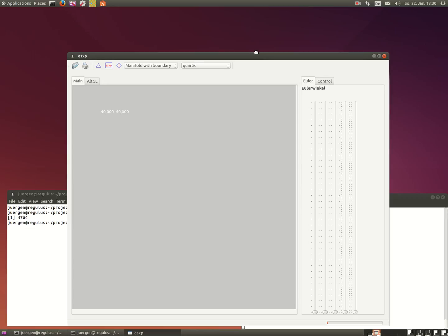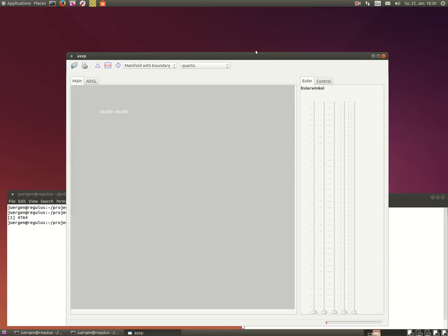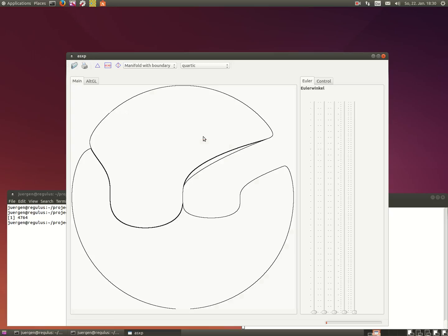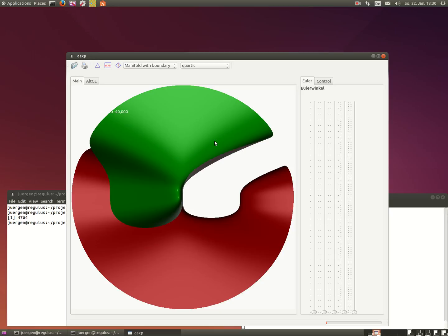First, let us now create some perspective views in one of the three main modes of view which asxp provides, namely silhouette, colors, and dots. Silhouette we take first. Silhouette, as can be expected, produces a silhouette view of the surface. Colors produces a colored view with a simple lighting model of parallel light falling from the direction of the viewer on the surface.